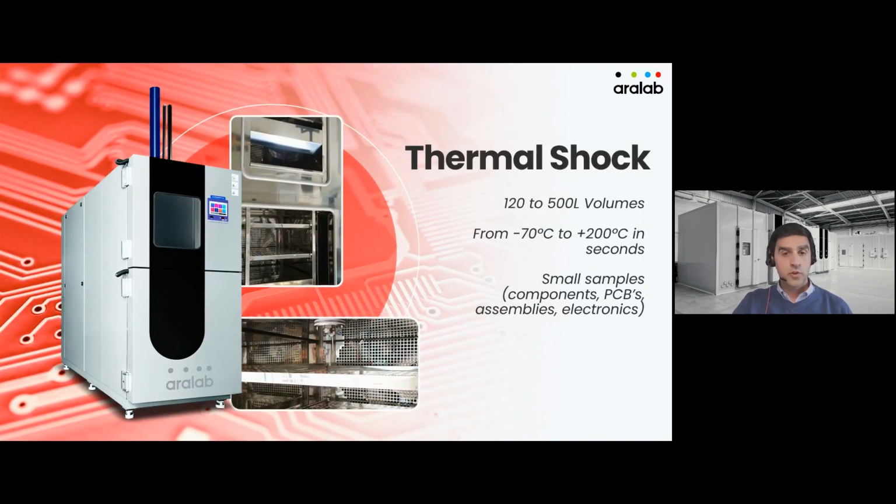What about thermal shock? So in thermal shock, again, same reasoning, several sizes available. And the difference in thermal shock is, I don't know if you can see my mouse, there's a basket inside of this chamber that goes up and down. So there's a hot chamber and a cold chamber. The hot chamber can go up to 200 degrees, and the cold chamber can go down to -70. And then this basket goes up and down the number of times that you want, and it promotes a shock.